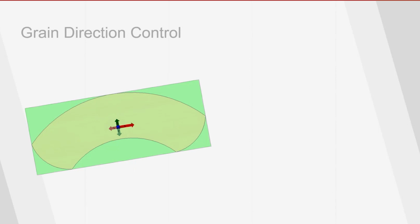A few more words about another functionality of the Material API. Through the API, you can control grain direction. When assigning a material, Woodworker Inventor automatically calculates the initial direction of the grain. It has its own solver inside and makes a decision how the initial direction looks. In other words, we can say that it determines the main face and sets a coordinate system for the Woodworker Inventor part.